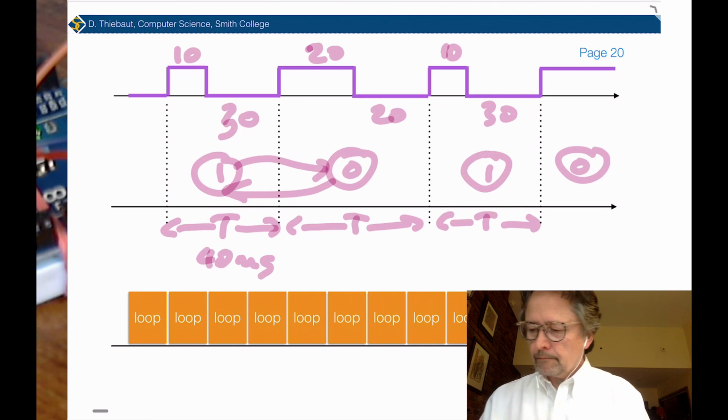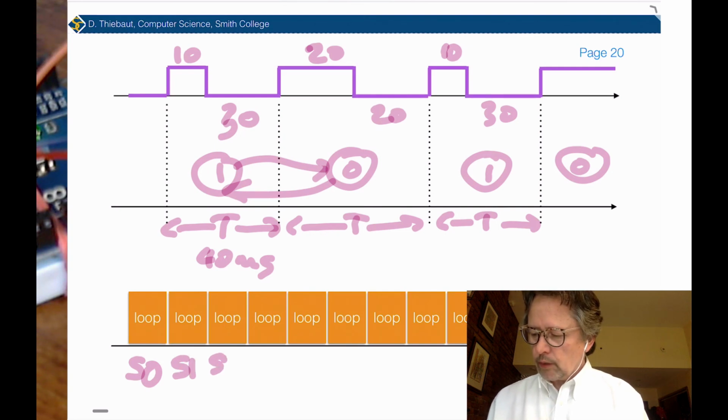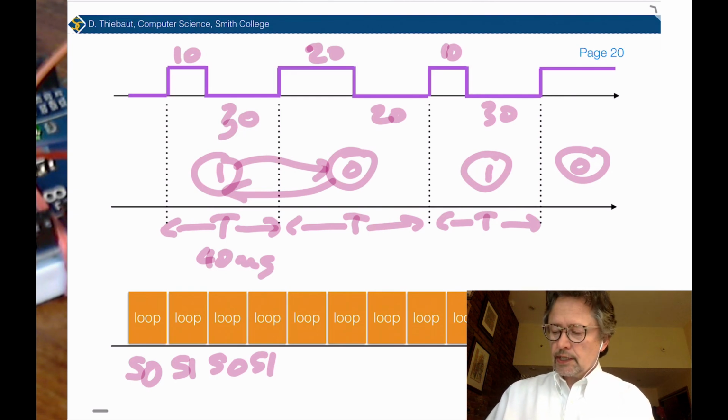And so instead of having a switch and looking at a switch, what I can do in my loop is say, all right, whenever I call the loop once, I'm going to be in state 0. And when that loop is done, it's going to change the state so that we're going to be in state 1, and then back to 0, back to 1. And what I will do in my sketch is check.